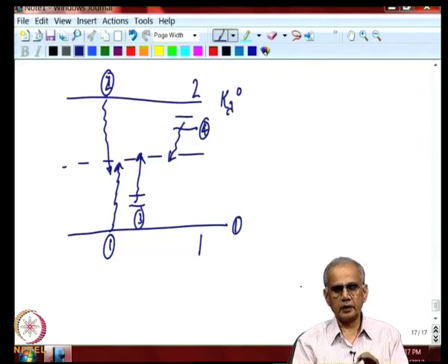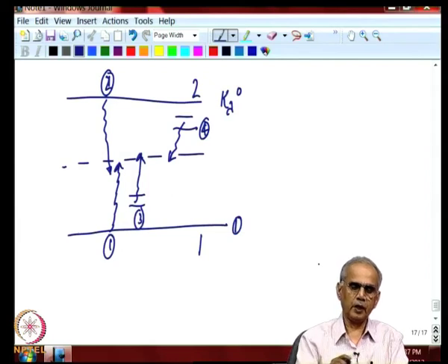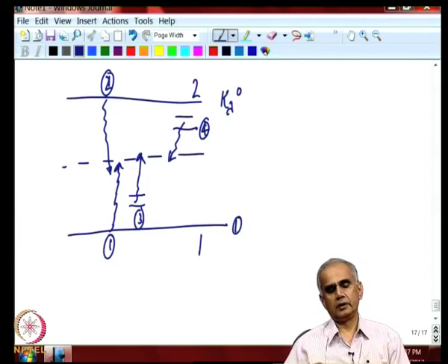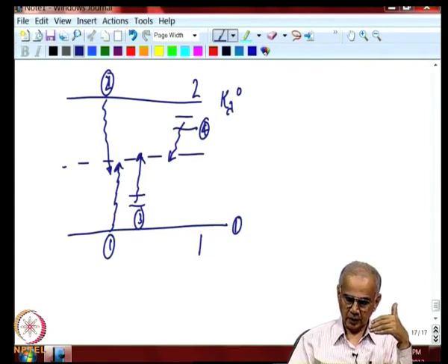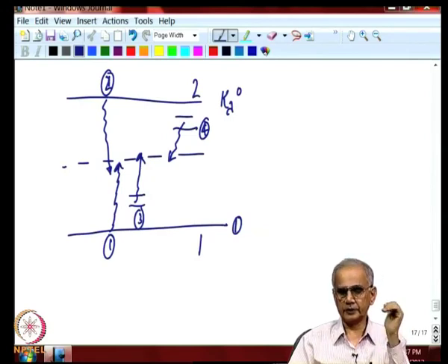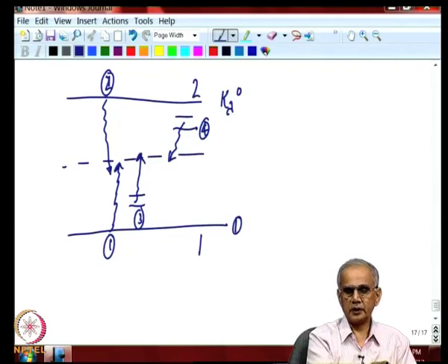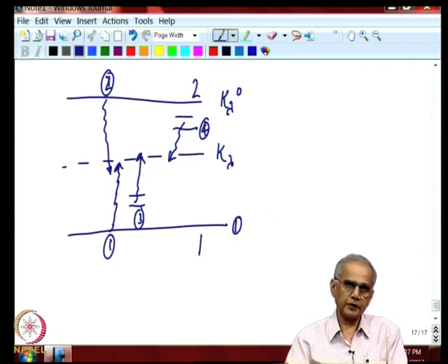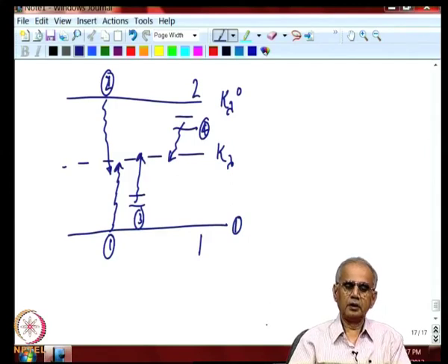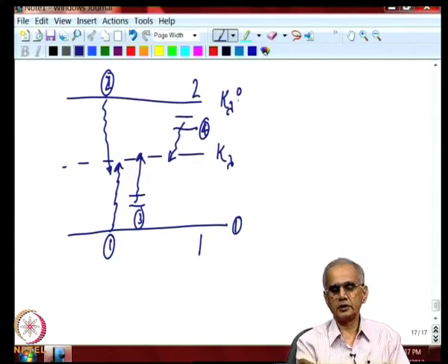So, you must fully understand the role played by these four streams. Stream 1 is the radiation leaving surface 1 either by emission or reflection, and after attenuation, which is angle dependent integration, reaches this layer which is kappa lambda. The second term is radiation leaving the top surface coming down to the level kappa lambda, and hence it travels the distance kappa lambda 0 minus kappa lambda to reach here.